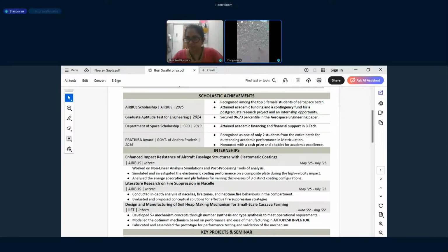What is M into x double dot? It is inertial force. What is C into x dot? Damping coefficient into velocity. What is that force called? Damping force. What is the force Kx? It is a spring force, a stiffness force.